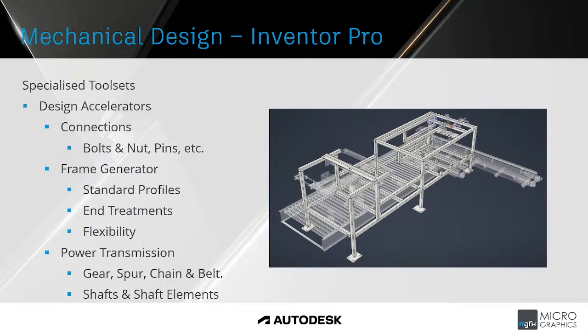That reference geometry can be changed. You can change the length of the reference, the width. You can adjust parameters around that reference component to adjust its size. And the Frame Generator will then automatically update the length of the tubes or standard profile sections that were placed on that geometry. So it automates the change process. You're not manually changing each tube length individually.